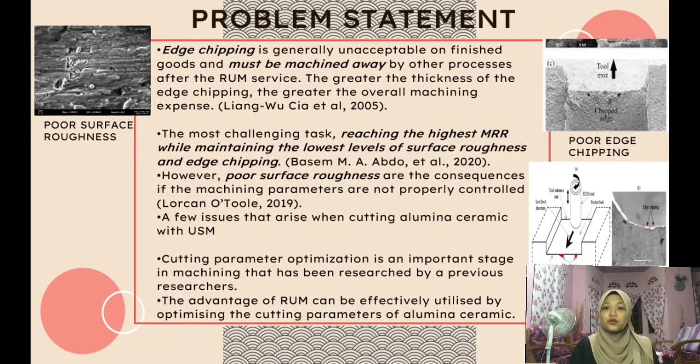Due mainly to excessive tool wear, low surface integrity, and high edge chipping of the machined components, conventional machining processes such as USM are unsuitable for cost-effective alumina ceramic machining. Stated by Al-Ahmar and others on 2018. Among the available contemporary machining methods introduced for processing typical and advanced material, which is ceramic, composite, hard-to-machine materials, and others, rotary ultrasonic machining RUM method has been observed as one of the best suitable candidates which fits for precise processing of alumina ceramic material, as this process produces thermal damage-free profiles along with high accuracy and enhanced material removal rates.